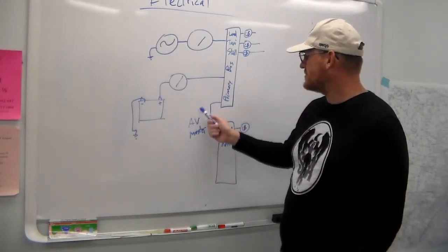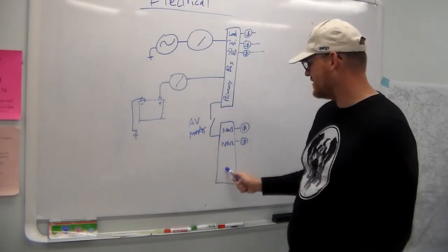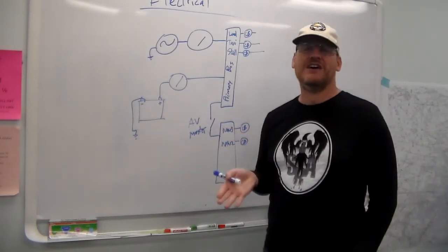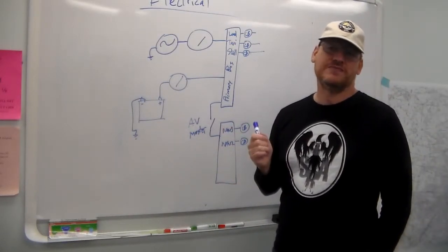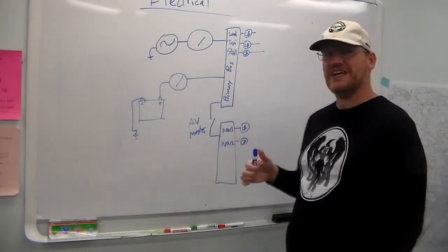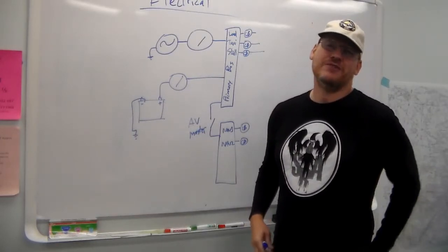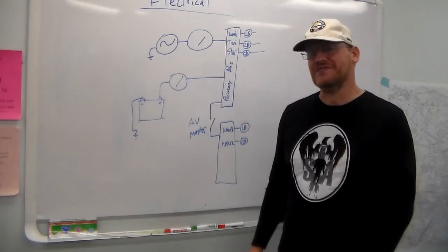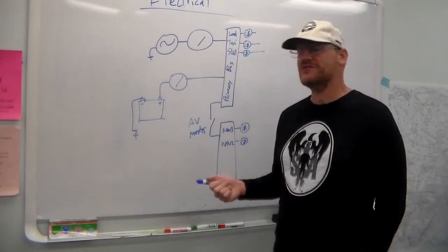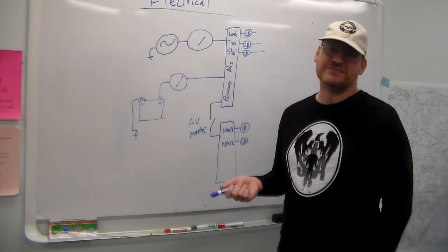That primary bus will be connected often through an avionics master to an avionics bus. So that way you can turn all the radios on and off with one switch, which has a number of advantages. Number one, it saves wear and tear on the individual switches on your avionics, because if those go bad, then it could be very expensive to fix that. It also makes it easier for you to turn stuff on and off during engine start and shutdown.